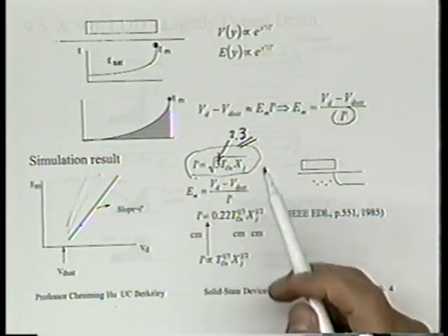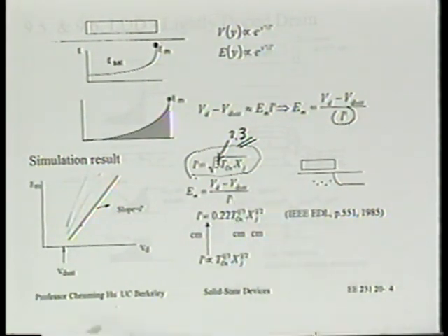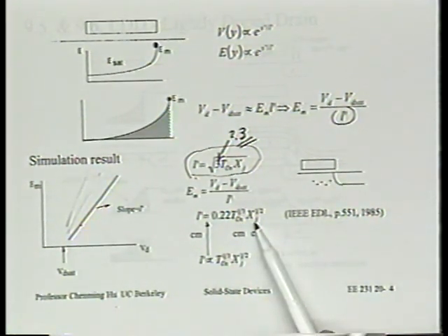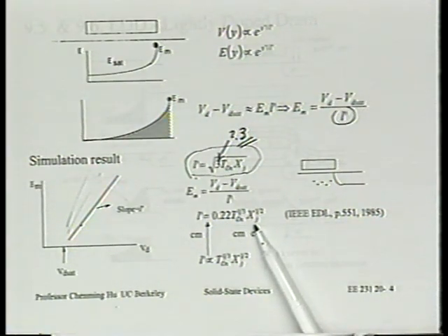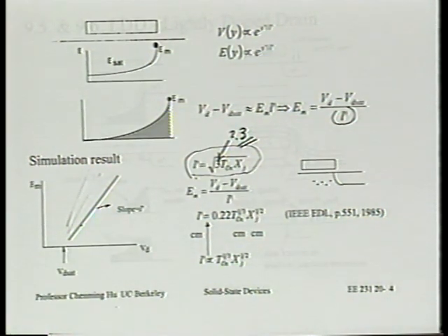I think we all agree increasing L prime is good. The problem is that the obvious way to increase L prime is to make the oxide thicker. And we all know there are several reasons we don't make the oxide thick. And also to make the junction depth thicker. Now this is more acceptable than making the oxide thicker. But even this is not good because a deep junction hurts the short channel effect, hurts the dipole effect, remember? And later we can perhaps address why there's this contradiction between hot carrier effects and the short channel effect in a more fundamental way.